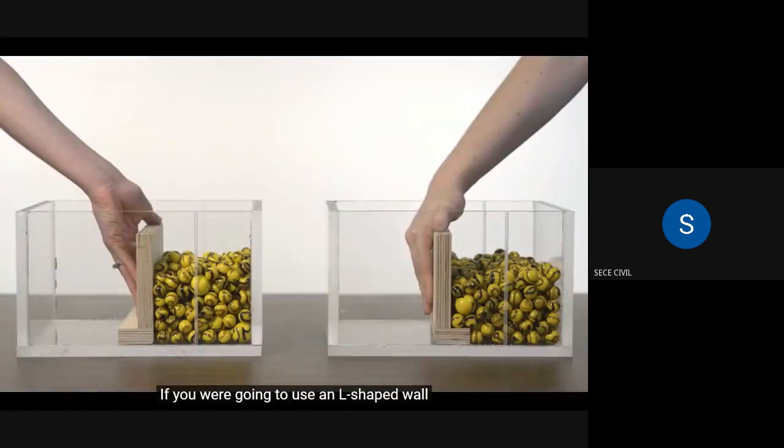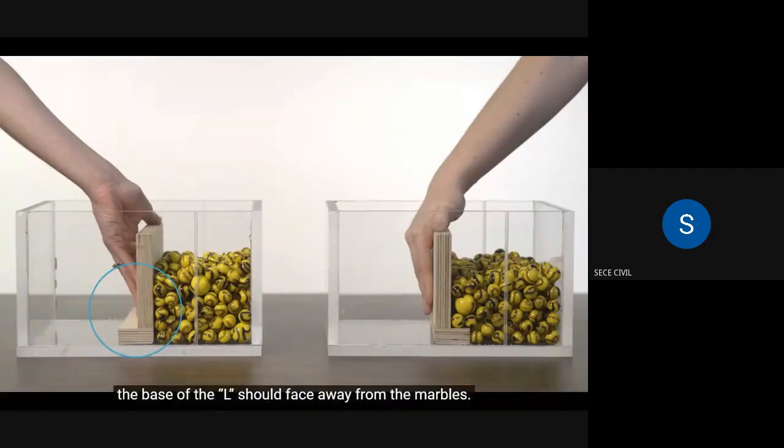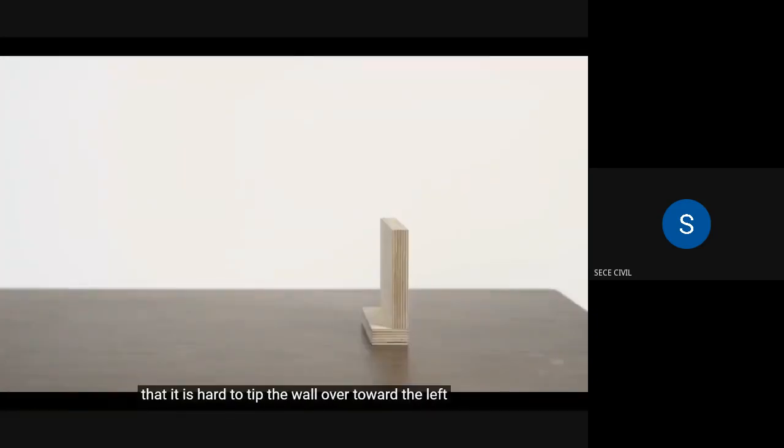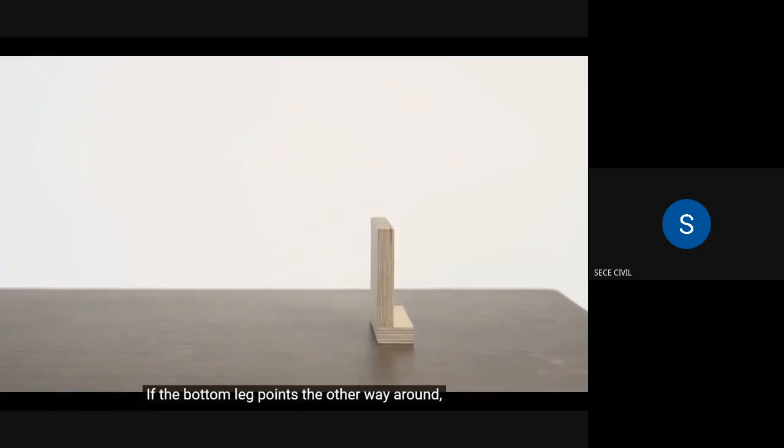If you are going to use an L-shaped wall to hold back soil and rock, as represented by these marbles, would you point the bottom leg towards the marbles or away from them? Many people would say that the base of the L should face away from the marbles. They probably realize that it is hard to tip the wall over towards the left if the bottom leg points in that direction. In engineering, we call tipping like this overturning. If the bottom leg points the other way around, it is easy to make the wall overturn. So easy, in fact, that I can do it with just a puff of air.